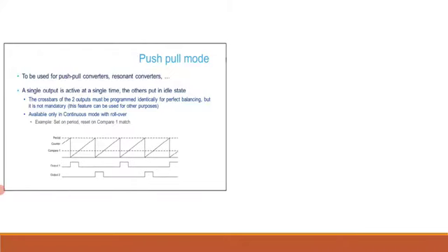It is captured in the HRTIM_CPT1R register and added to the HRTIM_CMP2R preload value. This yields an effective compare 2 value of 5 plus 7 equals 12. When the counter matches this compare 2 value, the output reset event is finally generated.